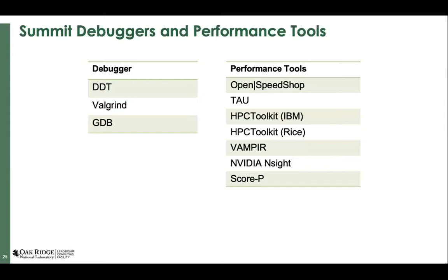So if possible, applications should move to using NVIDIA Nsight, because you can use it for collecting a timeline of your application and detailed performance information, even about specific GPU kernels. That is very helpful, and we've seen applications benefit a lot from using NVIDIA Nsight, especially for GPU kernel profiling.